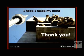Your second description of FAM, there's two buildings in Hong Kong in the 400 metre plus range that have completely vacant open floors at quarter points up the building. And the motivation had to do with fire suppression and other things, but it had the net effect of reducing the wind loads on the buildings. Would you put that in the same category as your FAM, even though it's passive?